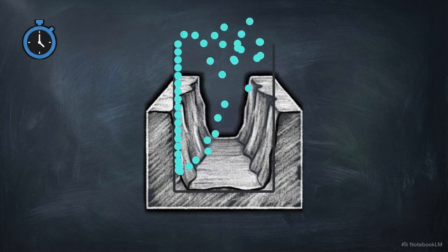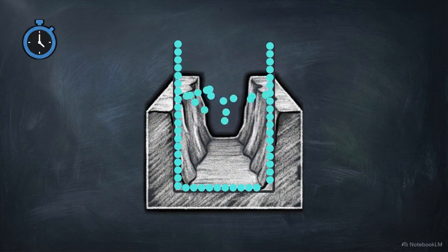When precursor A floods the trench, molecules bind to the walls to form exactly one atomic layer. Because the reaction is self-limiting, that layer physically rejects any additional precursor A particles from attaching. The ALD cycle operates chronologically.